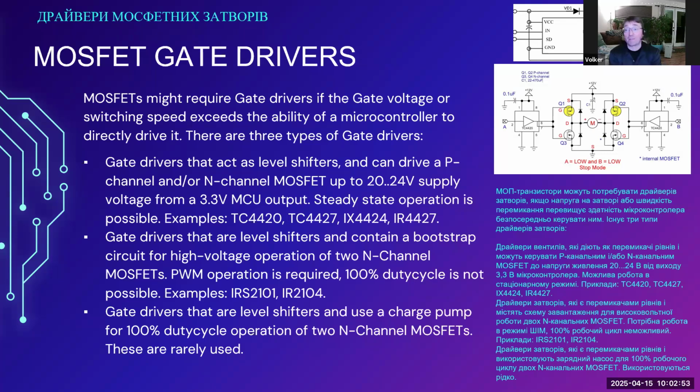What is the problem with this driver? It needs to keep switching. You can only use this driver in a PWM application. Once the capacitor has discharged its capacitance into the gate of the high side MOSFET, it's empty. For the next switching, it needs to be charged again, so the low side MOSFET has to turn on again.